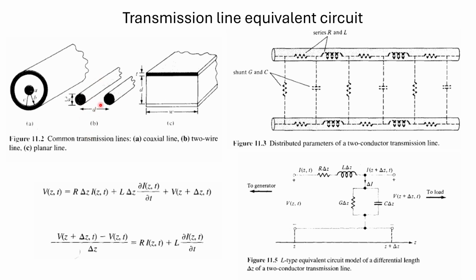So equivalent to this, you can draw this type of circuit. So here is nothing but R and inductor, that is resistor, inductor, and the capacitor and conductance. Conductance is nothing but 1 by resistance only. Equivalent to this circuit, you can draw it like this. So your resistor, inductor, and the conductance and the capacitor. So this is the part of your transmission line equivalent, right?